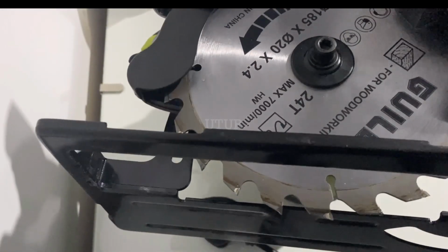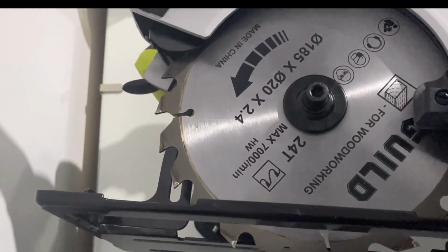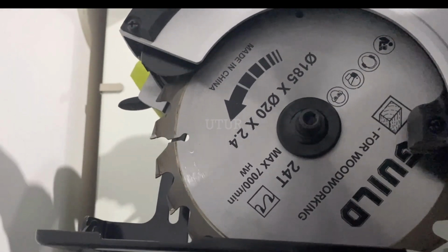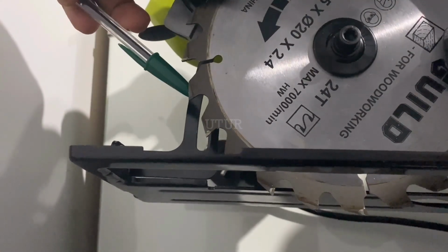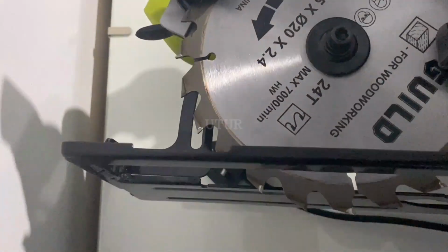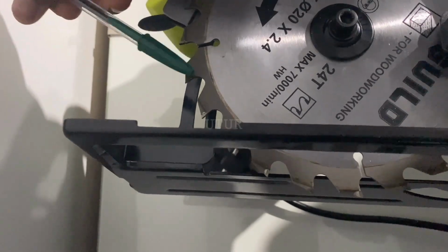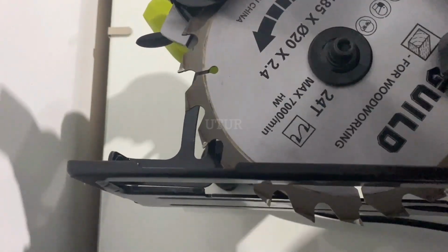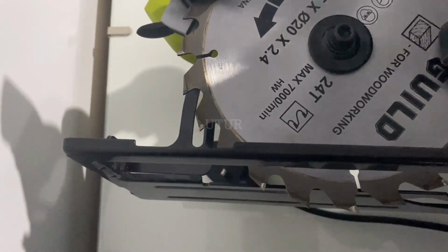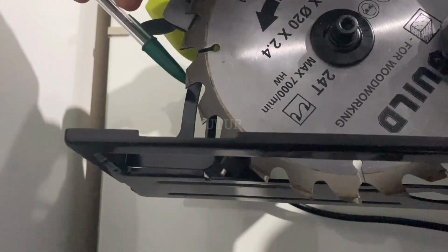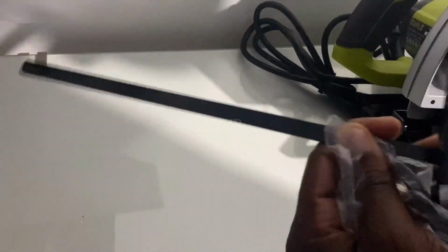So just a quick recap, when you're trying to get quality cuts, the blade selection as well as the type of material that you want to cut is very important. Here we intend to get strips off of hard plywood, and so the ripping blade with latch gullets, or the open hole technology, isn't the ideal blade for getting strips off of hard plywood. You should be getting a tooth configuration that's got the ATB, which is the alternate top bevel, as well as a combination composite or general purpose blade due to the grain structure of the hard plywood.